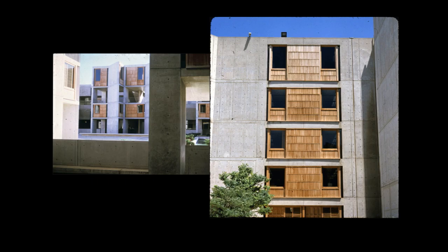You would secure those tension rods, and in that way, when the concrete was dumped in and when the pressure built and when the concrete was trying to push the formwork out, that pressure would be counteracted by the tension rods. And so that's what Kahn did. Obviously, at the end of the pour, once the concrete is cured, you'd pull off the formwork, and you'd pull the tension rods out of the concrete, which would leave a hole. And usually what they would do is they would send somebody around with a spatula and some wet concrete and kind of try to fill in the hole with wet concrete.